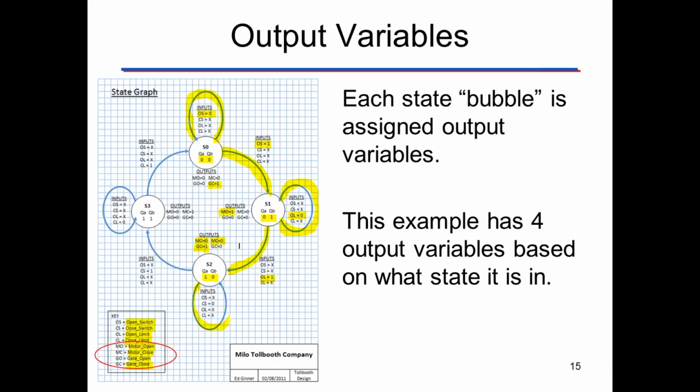We're in state 2, the gate's open, and we're constantly going around in a circle. The close switch, or close push button, maybe I should refer to it as a push button, is equal to 0. Nobody's pushing it right now. So we're in state 2, and we're staying in part 1 of state 2 right here. Constantly circling until someone hits the close switch.